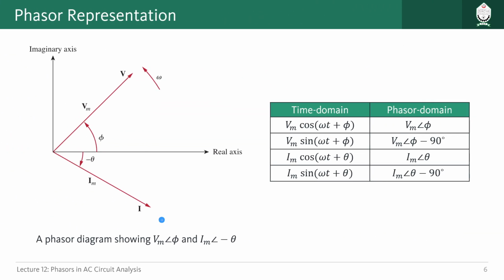Now if we understand phasors, then this particular thing here is the phasor diagram. We can always represent each of the phasors in this diagram. This is just a simple complex plane. This is the real axis, this is the imaginary axis, and all the vectors or all the phasors we get for all the sinusoids we have in the circuit, we can represent those here using a vector, because all of the signals will have some amplitude as well as some phase with respect to our horizontal axis.